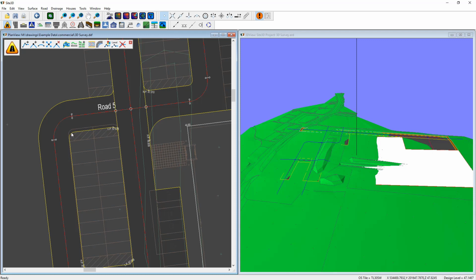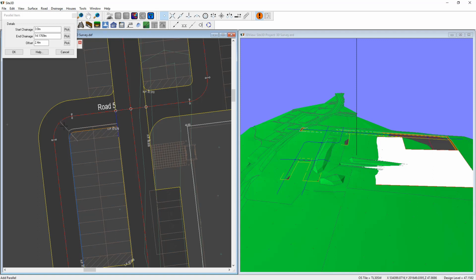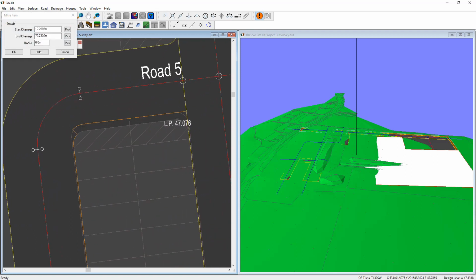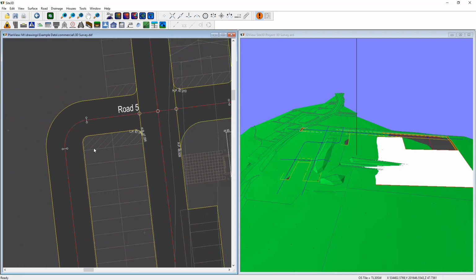So now I just need to very quickly edit this one's channels and make that the new width. So from the beginning to somewhere halfway around that corner at the new width of 2.4499, that's going to be 2.45, isn't it? It's letting me see the values that I'm picking, you see, and I can then verify whether they're correct or not, so I can update them. Okay, and then use the miter tool, turn off the snap, and say, well, I actually want to refill it this time rather than just finding the intersection point. So I want to extend this straight and this straight, and you can see it's giving me an unfilleted one, and then I know in this case it's going to be a 1 meter radius on that one. So it's now filleting those two straights with that one radius. And then apply. Done.